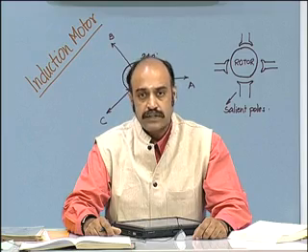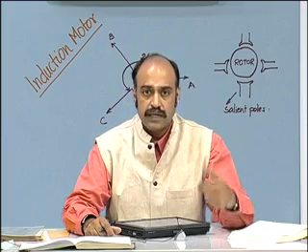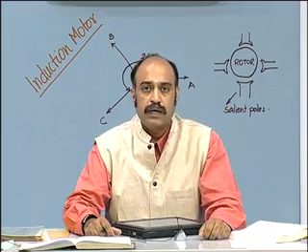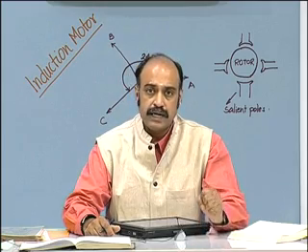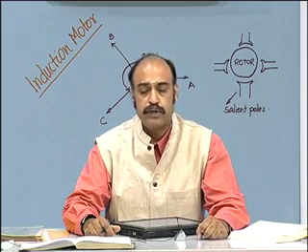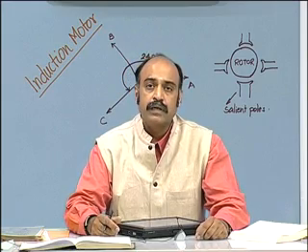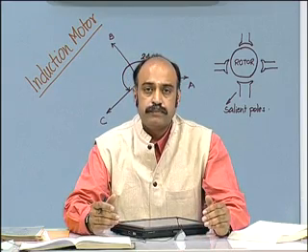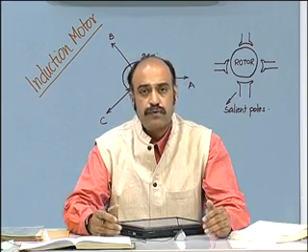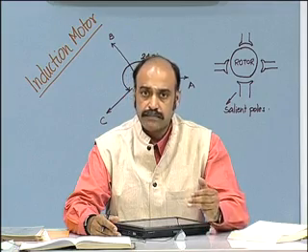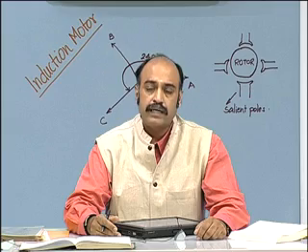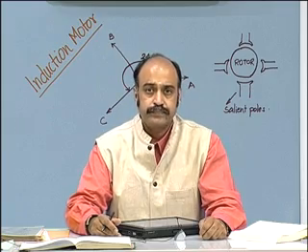Of course, the rotor conductors in the squirrel cage are shorted, which means a huge current flows in the rotor conductors. This current interacts with the flux produced in the air gap and provides a force which makes the rotor conductor move to try and catch up with the field.